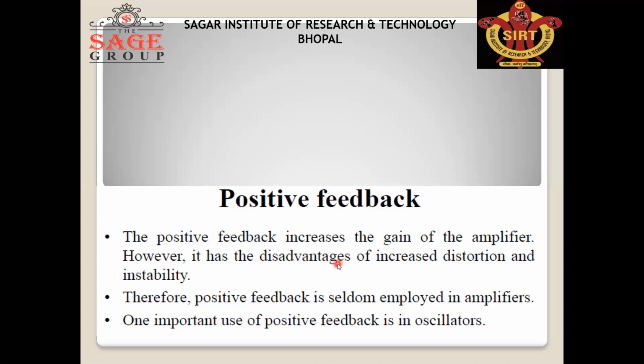And positive feedback also increases the instability. Instability means due to rise in temperature and other transistor parameters, the transistors become unstable. So if we use positive feedback, instability will also increase. That's why positive feedback is seldom used in amplifiers. And positive feedback is used in oscillators.